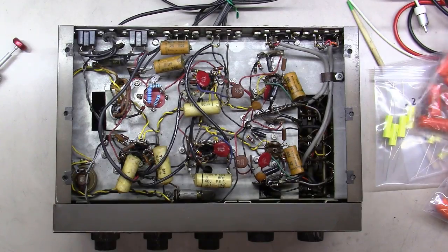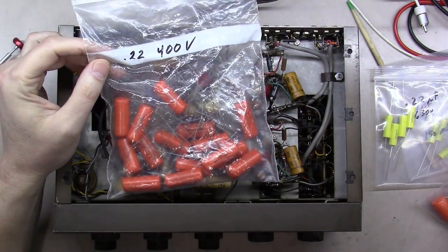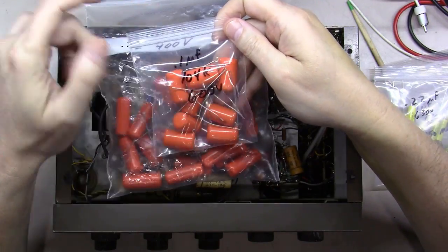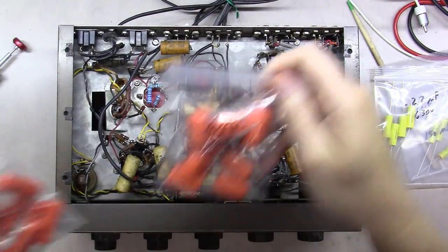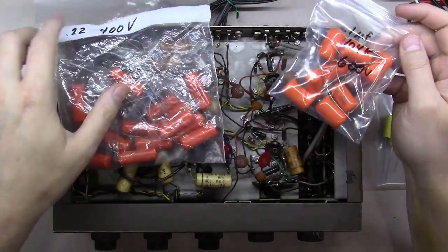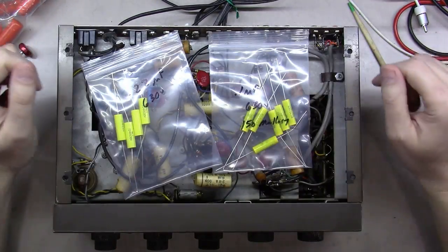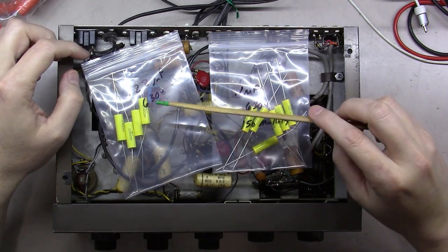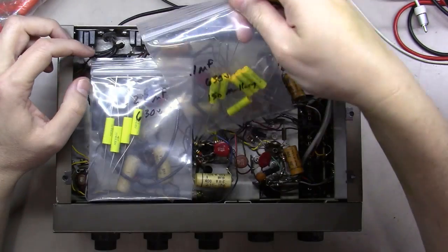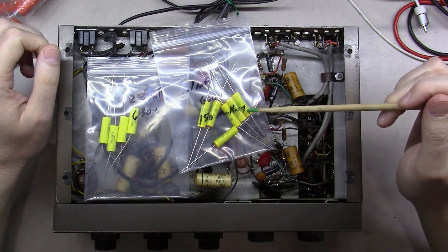Alright, so I've gone in here and I've looked at what I've got. I've got 0.22 microfarad orange drops. I've got some 0.1 microfarad orange drops here at 600 volts. Could use both of those in here easily. One thing you'll note, these orange drops are fairly large in size relative to the counterparts here, what we could go with. These are 0.22 microfarad, 630 volts, and 0.1 microfarad, 630 volts, the 150 Mallory M series.